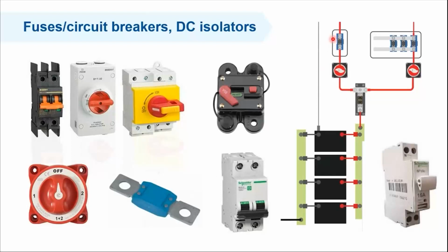A device might withstand the high current for a longer time, but cables get heated when there is a high current, and then they can start a fire, and it's a disaster. So fuses need to protect the cables.